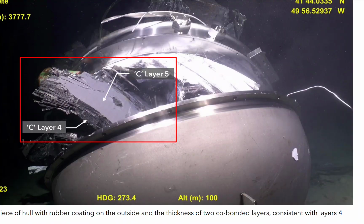And this is what I just said, where it tucks. Here's the interface ring, layers 4 and 5. They shear off the other side of here. They shear off, tuck under, as I said, and they come into here. They come into and push into the back of the dome. The dome's already been impacted this time by the bottles and pushed it away, because we don't see this compressive moment here where it actually buckled it.